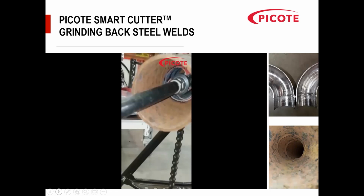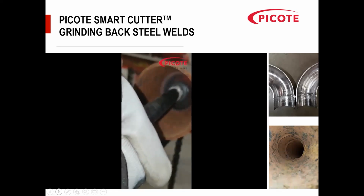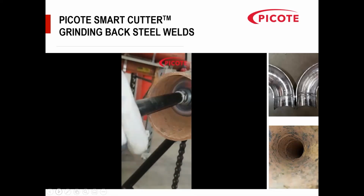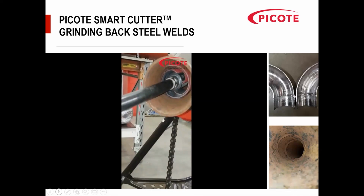The power of it is that we were asked by a company that does a lot of steel fabrication. One of the problems is when you weld the steel pipes, you've got that internal bead, and when that internal bead is on a bend, it's very hard to remove. So they approached us, and they then brought the smart cutter. As you can see here, as it's rotating, the grinding panels come out, very aggressive. And like I said, you can see on the photographs on the right hand side that it ground away the complete weld on the inside to make the pipe smooth.